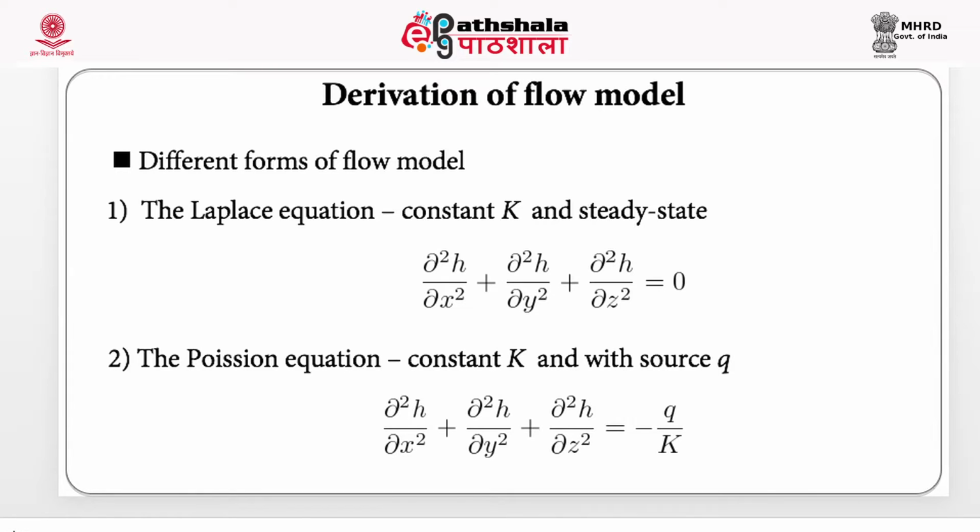Now this is a very special boundary condition, because it is also used to define the no flow boundary condition, and this can be done by making dh by dx, or the gradient, equal to 0. If there is no gradient, there is no flow, and this specifies the no flow condition, or water not flowing or passing the boundary.